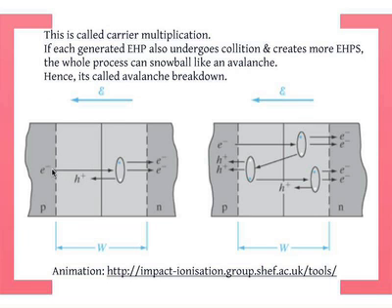So this is the one electron-hole pair. You have electrons coming in, you have an impact ionization going on here, the hole goes this way, and the two electrons go this way. That's what we just saw. But we can also have a situation where the electron comes in, you have an impact ionization here, an electron is created, and another hole is created. Now the electrons went away to the other side.